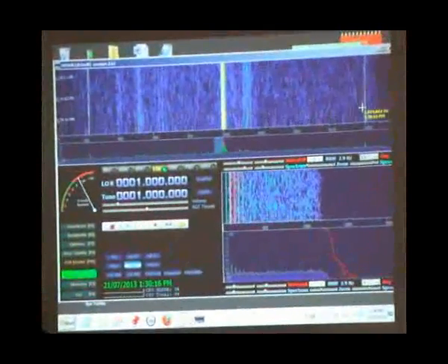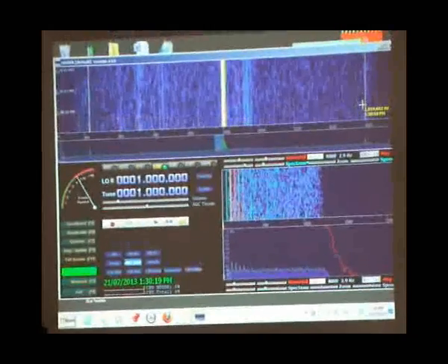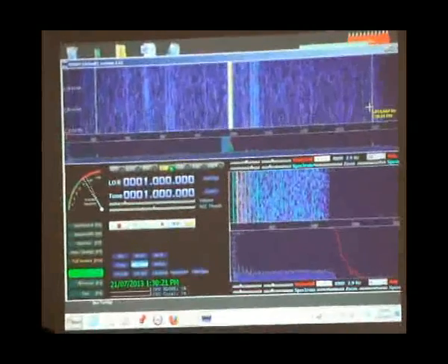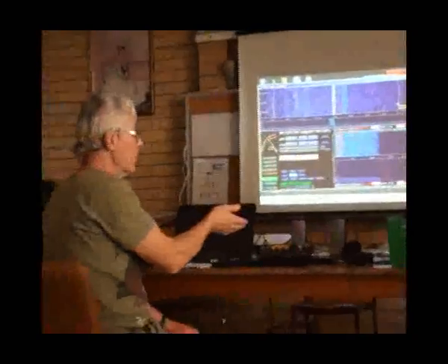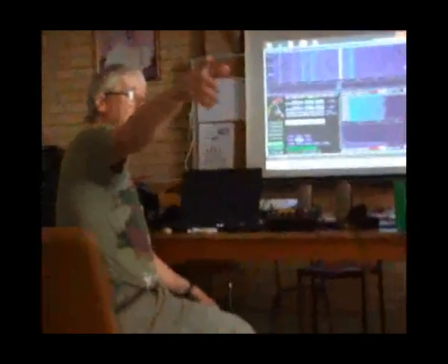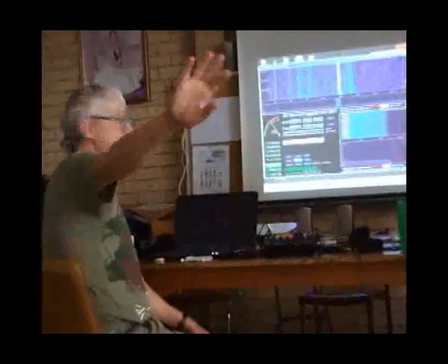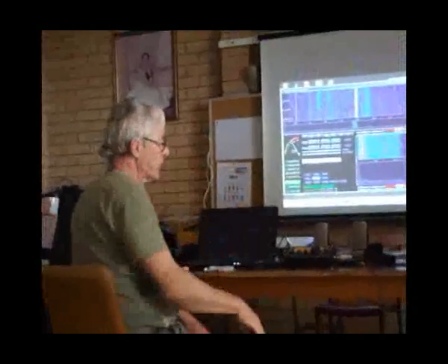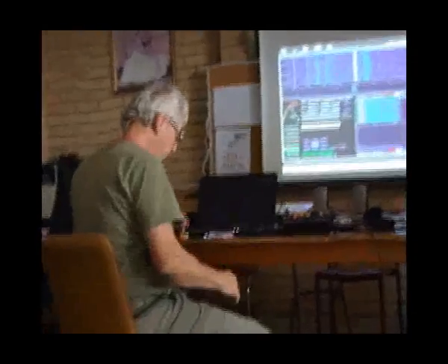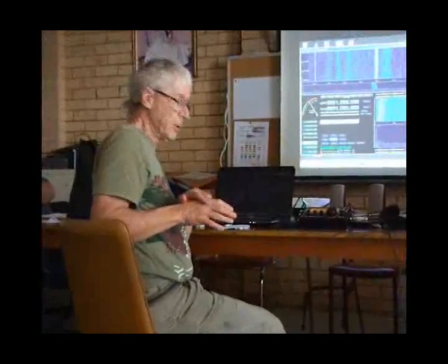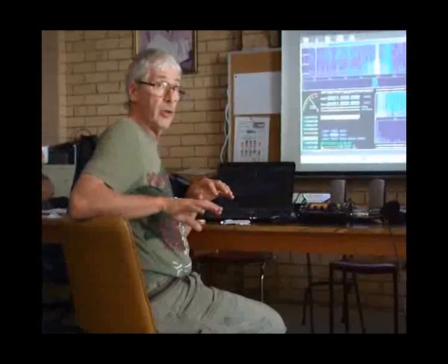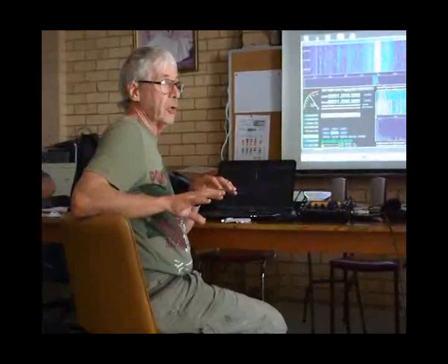But to use it, you have to have the right kind of input that it can make sense of, and it uses an IQ input, which is used by software-defined radios or receivers, like the one that Jeff's got set up in there, which is a receiver only. But it puts out what they call a phase quadrature signal. It doesn't have IF stages as a conventional radio does. You wouldn't call it single conversion either, but the architecture is quite interesting really.